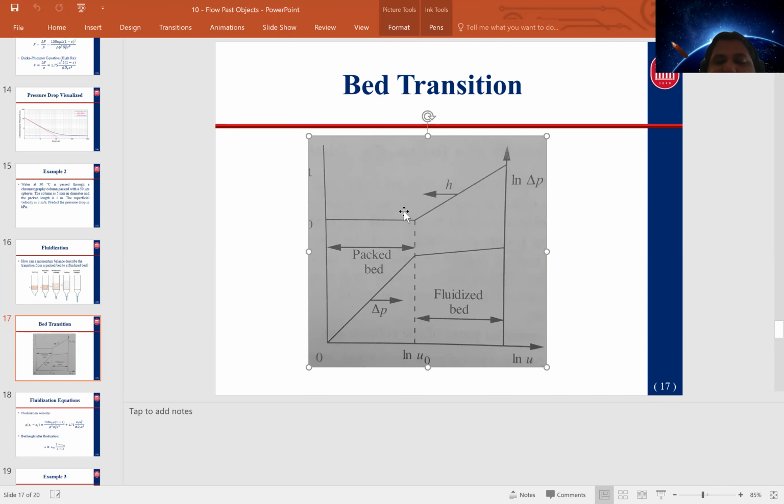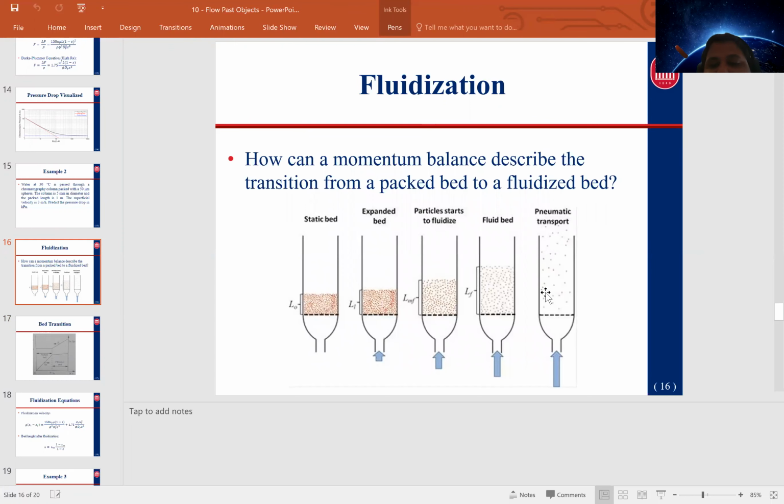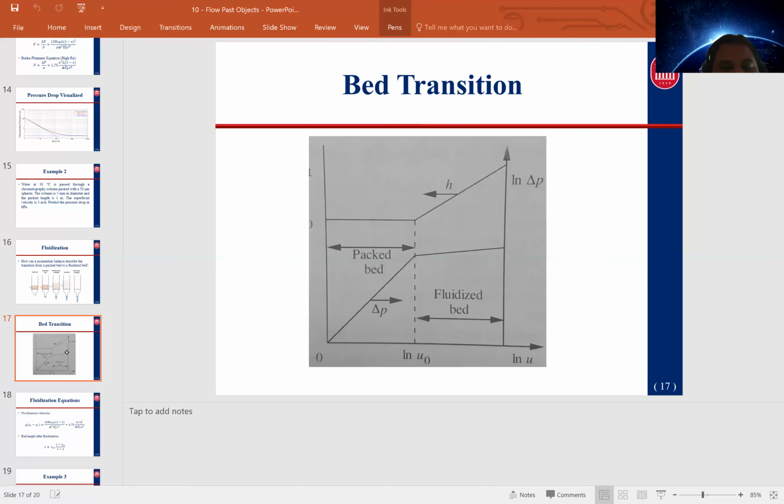Instead, once you have a fluidized bed, we see a proportional increase in our bed length. And so we start to expand the bed rather than gain a greater pressure drop, because at that point, the fluid is literally able to push the particles out of the way and not have to lose a whole lot of pressure energy because of it. Now, if you go too high, what you end up with is essentially washout, where you don't have a bed anymore, you just have stuff and a headache downstream. Any questions on that?